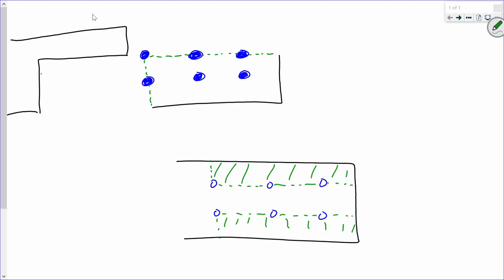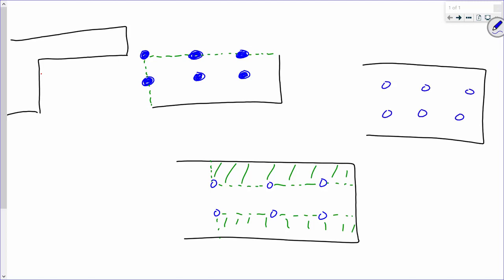So the one up top is a possible failure path. This is a possible failure path. Another possible failure path is this over here, if I cut this out and that block ripped out. Again, use the analogy that it was a sheet of paper on corkboard and each of these bolts were little thumbtacks. Cut that out, the paper can't stay there. It will fall off. Is that a fair way of looking at it?